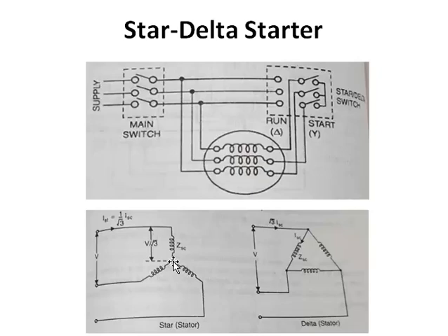See, one end of all the windings is connected or joined, and the other ends are free. This is called a star connection. During starting, we put it in the star connection. If you put it in the star connection, whatever the applied voltage V, how much voltage do we see across each stator winding? V divided by root 3. So it gets reduced by 1 by root 3.